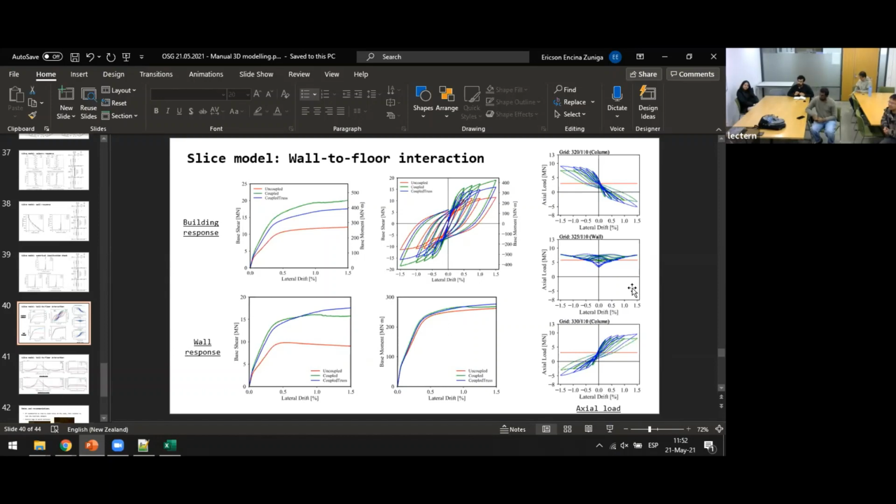So your system is more stable against bending moments, against overturning actions. That means that you are stronger, and therefore you can receive more loads, because now it's even more difficult to overturn you. But what resists shear is just you, not the poles, because the poles are pinned, so they cannot resist shear.